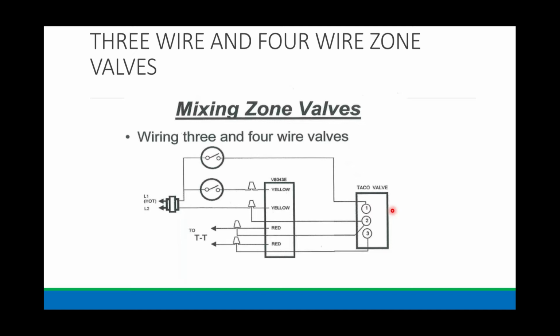Now, how can that be? Well, it's a heat motor valve. So what happens is we have a wax pill, and we've wrapped it with copper wire. And when we energize the copper wire, it creates heat, it heats up the wax, the wax expands, and it pushes down a plunger, which is going to open the valve. And on one side of that plunger is half a switch. At the bottom, when it completely opens the valve, is the other half of the switch, and when the 2 sides meet, we've now closed the end switch. That also means we've broken the connection at terminals 1 and 2.